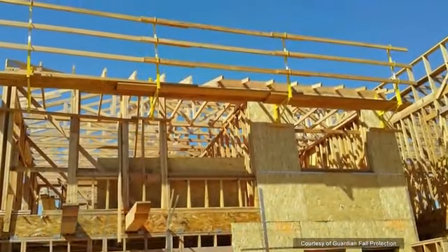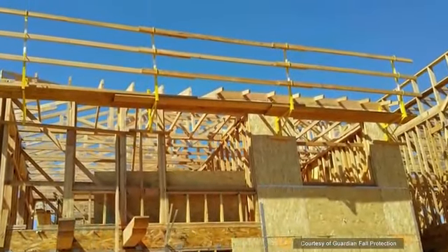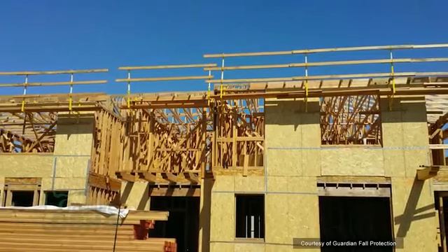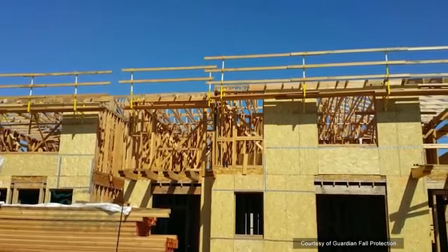One of the other fall protection systems that I've seen mainly framing contractors use is scaffolding, or carpenter scaffolding, where instead of standing on top of the wall plate to, say, set trusses, they're standing on a built-in scaffolding system. It's a couple of feet down from the top of the wall. And that way they actually have better leverage with those trusses, and they're not exposed to the fall to the outside of the building. They're in better control, and they don't have that hazard there.